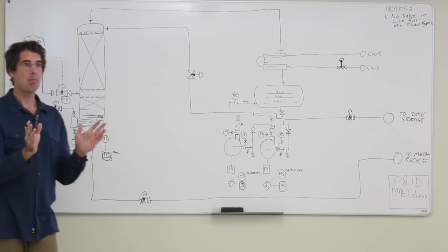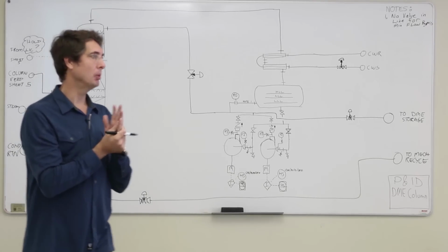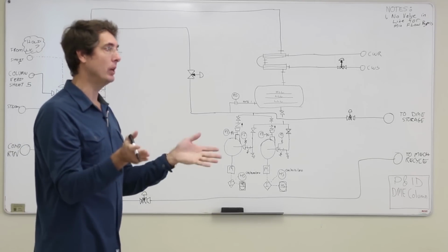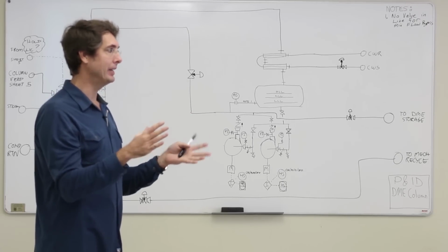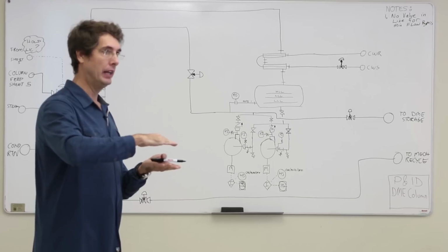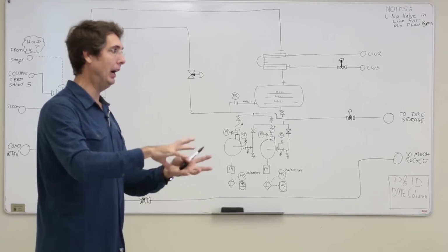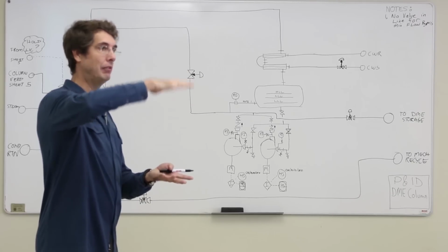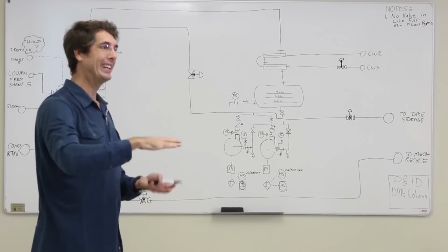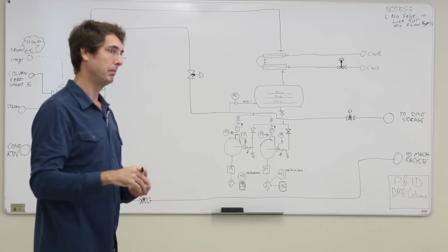But the game here, it's not that simple sometimes. It's like when you're boiling potatoes on the stove. Sometimes you start to boil it a little bit harder, and you start to create bubbles in the material, and it actually causes the liquid level to rise. So it can fool the level transmitters.